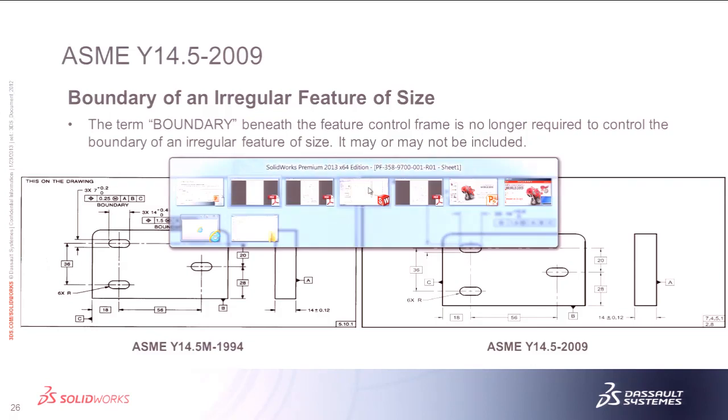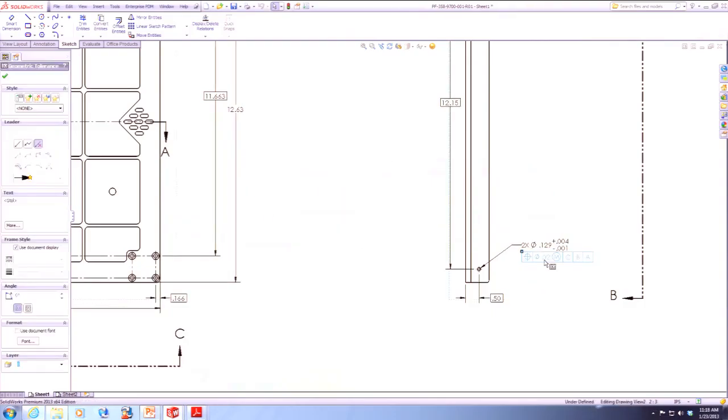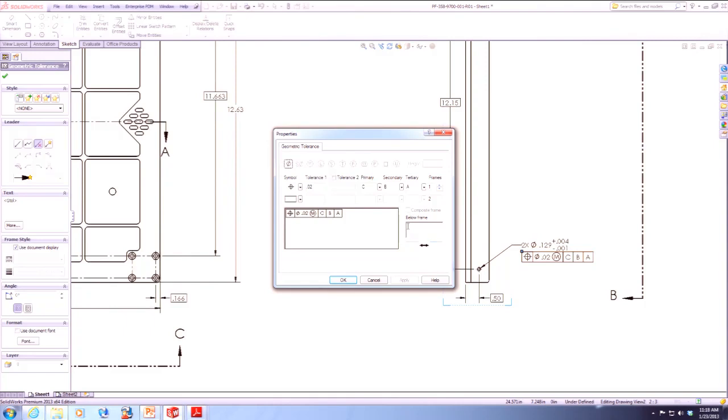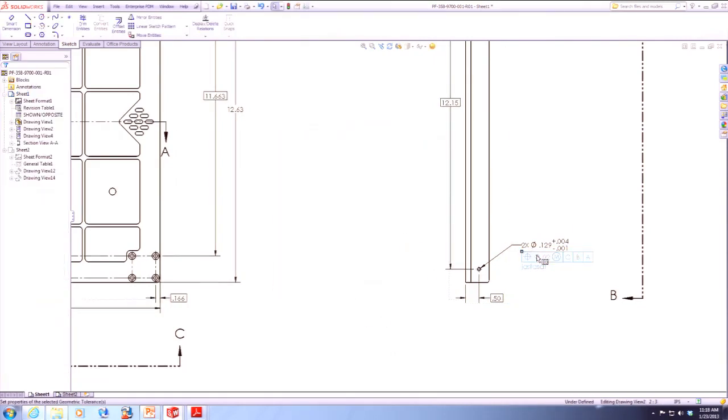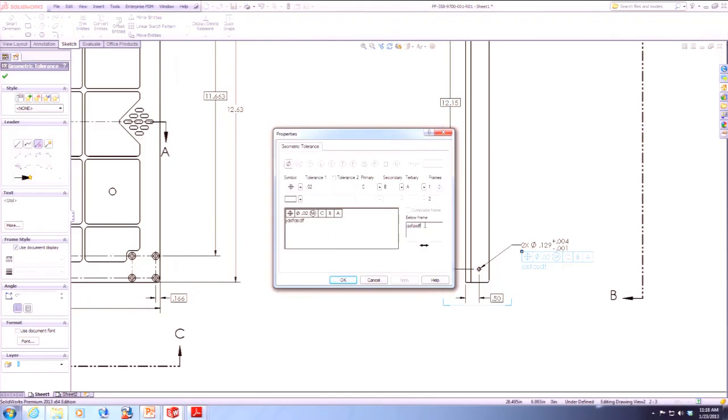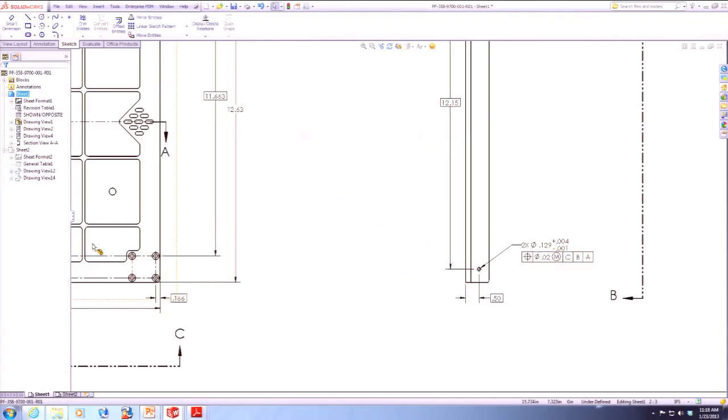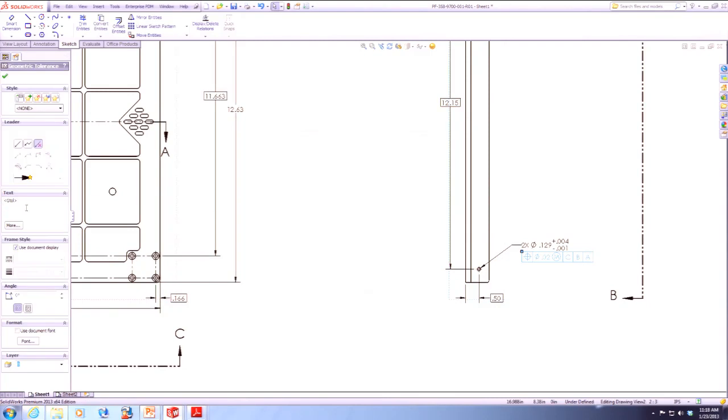And just real quick thing so people know, now in SolidWorks, you have a note block here where you can put things in. So you can say separate requirement or whatever the statement is, put it in, and it shows up directly below it. When I hit OK, the other option to do it, this was brought in, I think, in 2012. You've always actually been able to put it over here in the text in the properties.